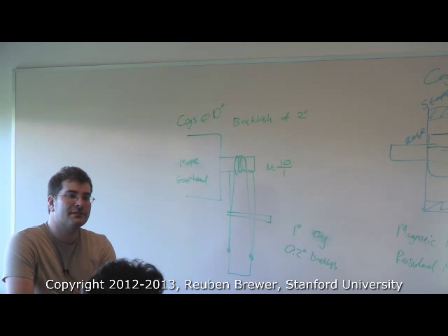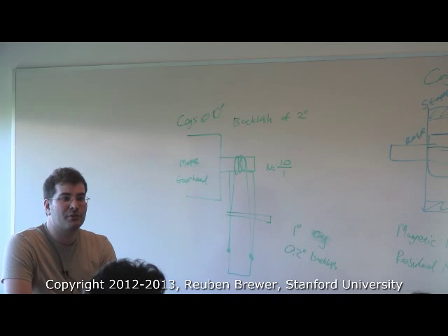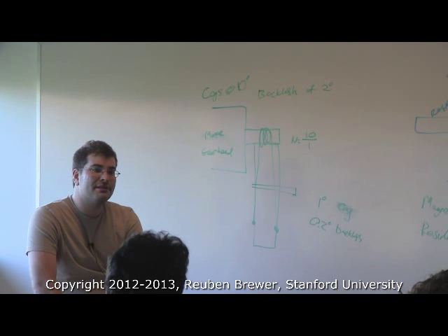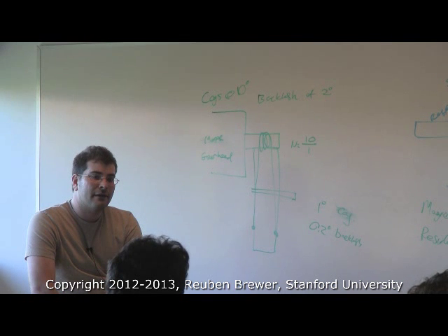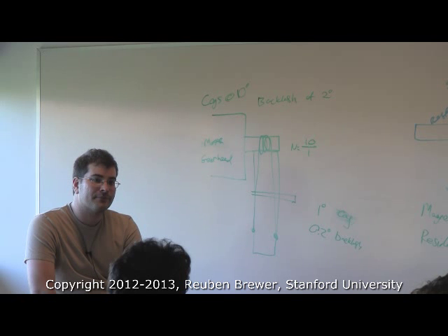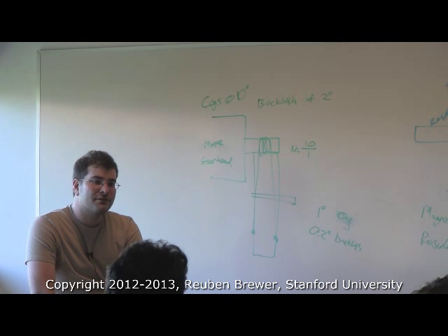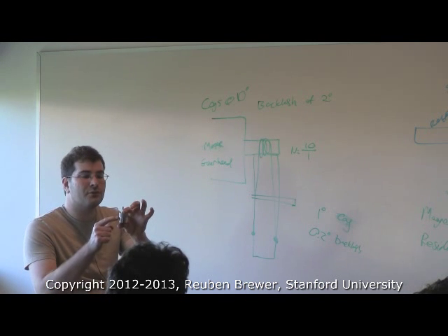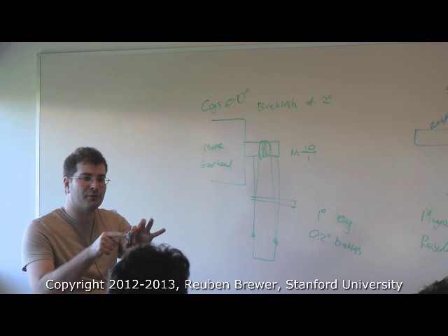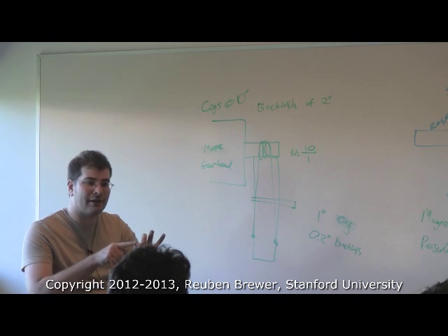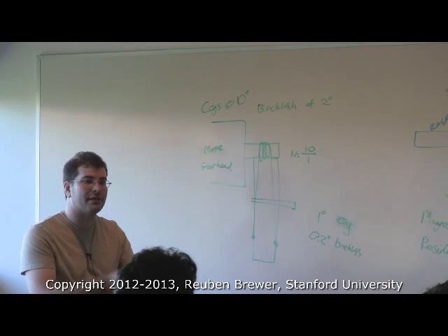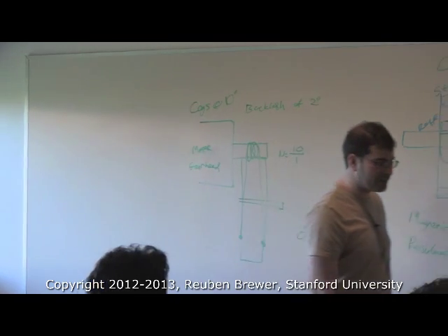If I split the gearbox into a nice compact 10 to 1 and then a nice compact 10 to 1 cable, I've divided my backlash by 10, and I got it basically for free. So oftentimes when I throw a gearbox on something, I'll split it. I'll use a motor with a gearbox, but if I needed 100 to 1, I won't buy 100 to 1. I'll buy 10 to 1, and then I'll have a cable transmission or something to take the backlash off of this and divide by 10. It's a smart way of dividing.